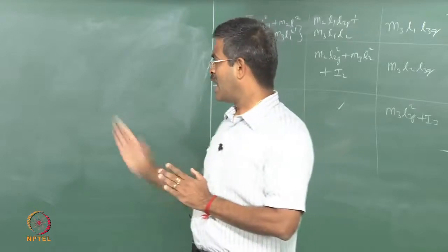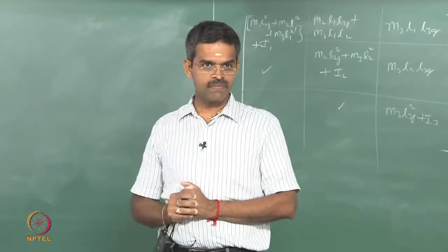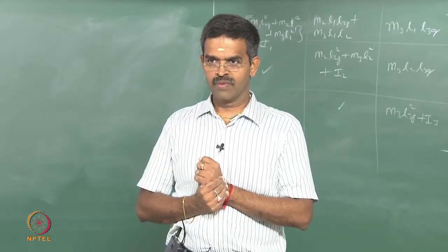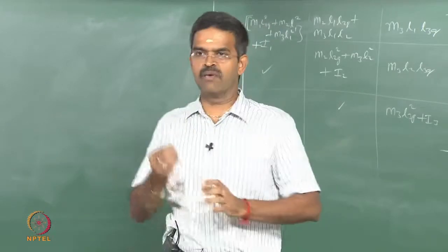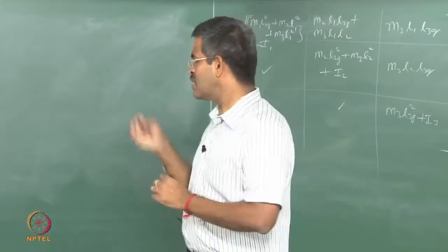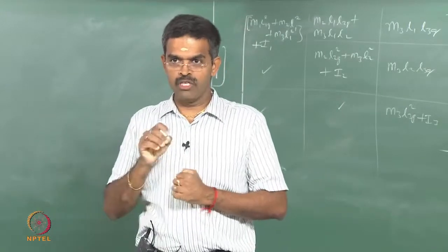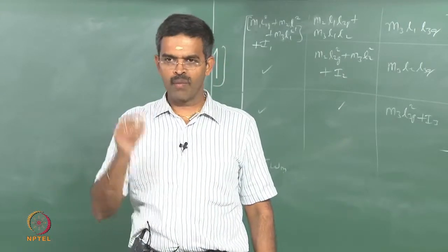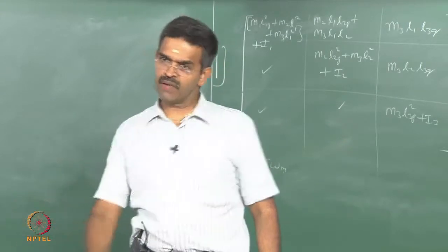The physical problem is that I have a K-M system with large displacement, which I want to control. I am controlling it by putting a secondary mass system on it. Now I cannot analytically solve this problem straight away because I am going to tune it to the maximum response of the primary system, which will happen only when omega equals omega bar, the excitation frequency.